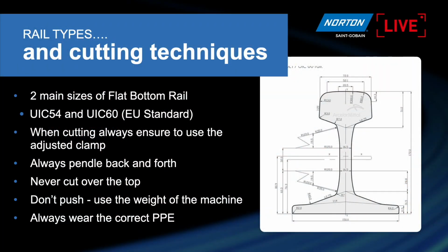Okay, so we understand why they have to cut rail, why they actually do that rail, the machine they're used on. So let's have a look at the different types of rail we have in the market and a few techniques that we use when cutting. There's two main sizes of what we call flat bottom rail. As you see on the picture there, you can see the flat bottom of that rail section. That's UIC 54 and UIC 60, which is an EU standard.